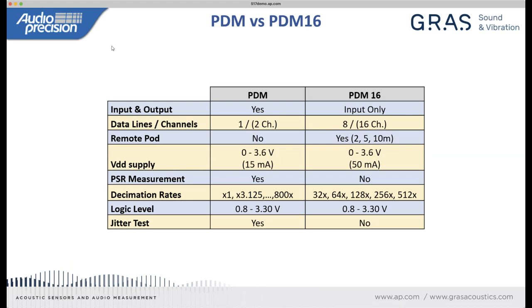And also from a signal integrity point of view, most PDM microphones cannot directly drive a very long cable. So it's always been a little inconvenient to use the PDM module when testing a microphone that's far from the amplifier. We do have a PDM line driver accessory that's a little bit different than the PDM16's remote pod.